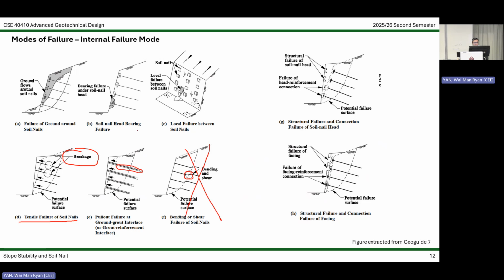in terms of internal failure. And in terms of some local failure, for example, erosion, bearing failure, and there's some unreinforced area, again, normally we don't check. The reason behind is the practice in Hong Kong. For example, nail distance, the spacing, we do have some guideline. For example, horizontal spacing, normally smaller than 2 meters, horizontal.